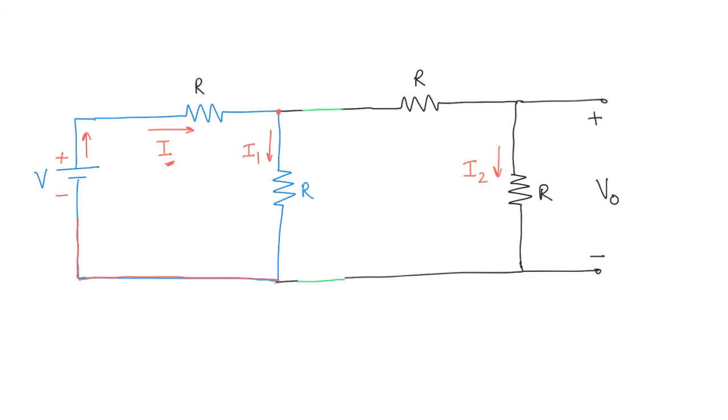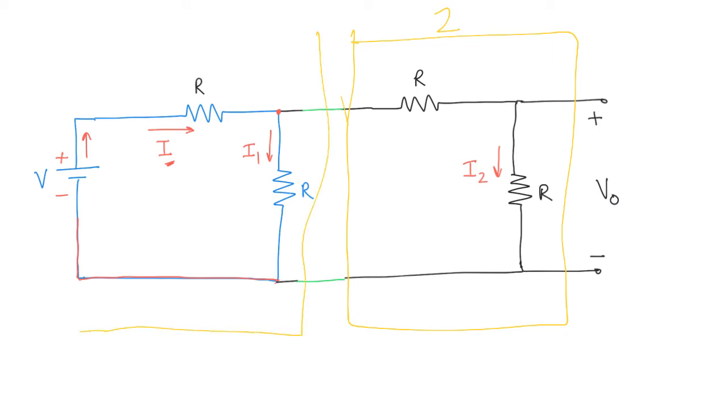Right? So this thing is circuit 2. So circuit 2 has somehow influenced, and we have just seen the mechanism of influence, circuit 1, basically by changing the amount of current that flows through this resistance. And this is a problem that in electrical terms is called loading.